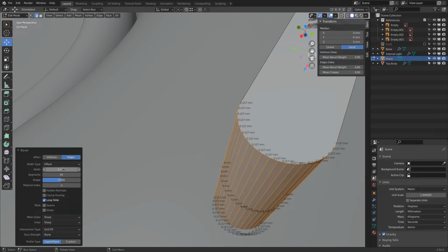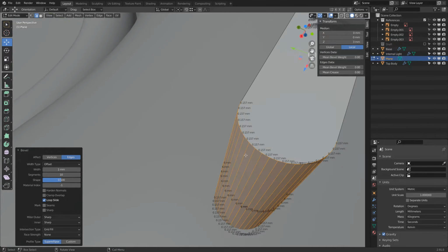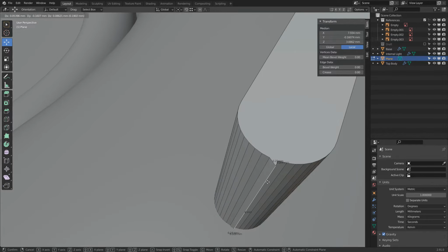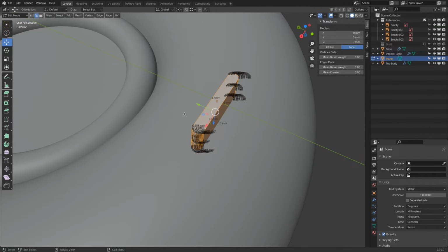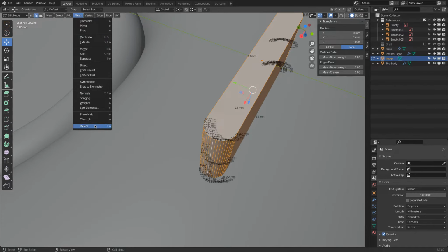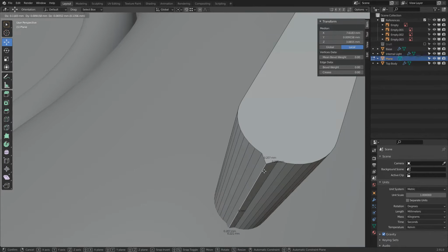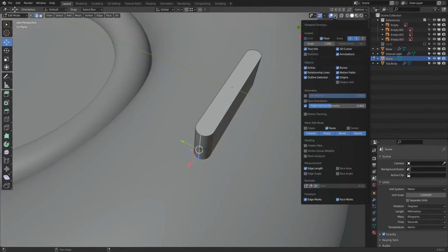So we can actually, okay, let's do this. We go 1 because this is an object of 2. So with a bevel of 1 is 2. Okay, this is all fine. But what we will end up with, you can see there are some extra edges because there are two arcs that are touching each other. So press A, select everything, then we go mesh, clean up, and merge by distance, and there should be 4 points being removed. There are like 2 points for this line and 2 points for that other line.